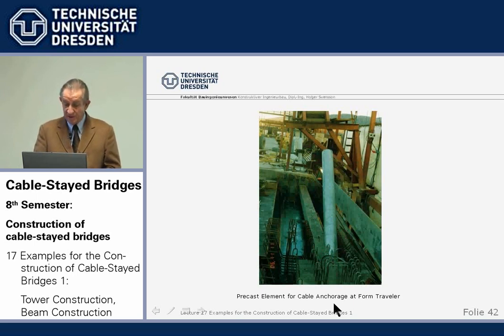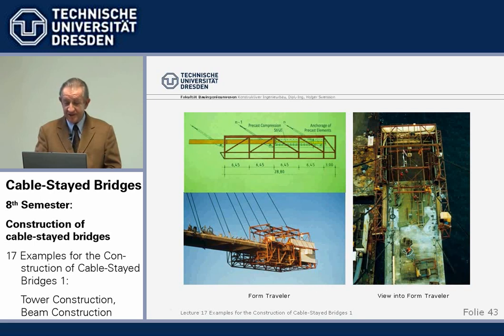So the final cable was installed with low force, the vertical component taken by the bolts into the forms, the horizontal component taken by the strut into the already erected beam. And we were quite happy, except the handling of the precast element then wasn't so. Contractor was there, there must be a better way, but still, we liked it already. We see it here in detail.